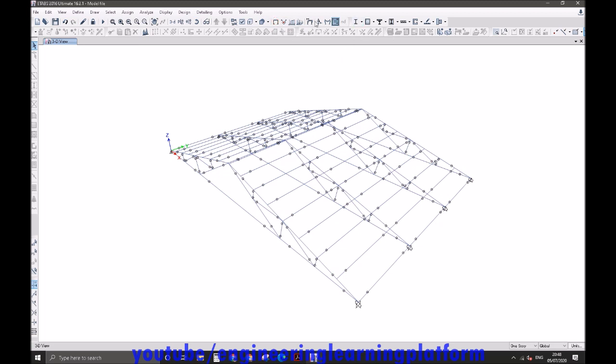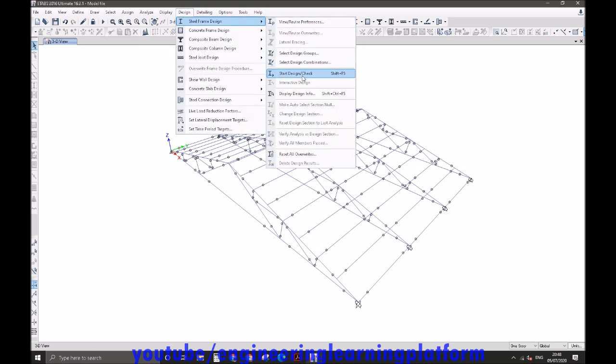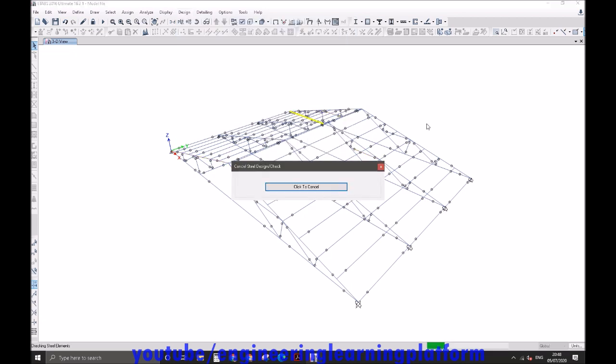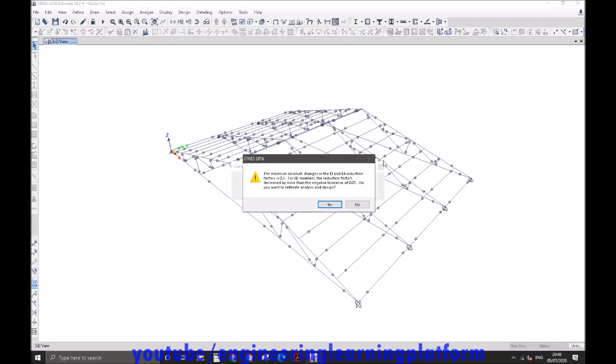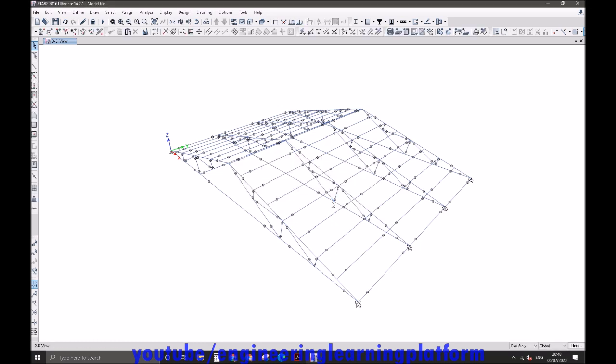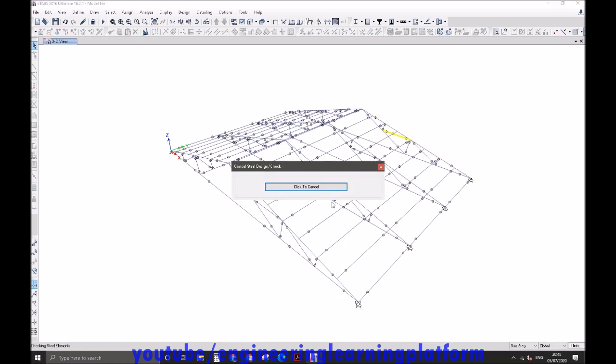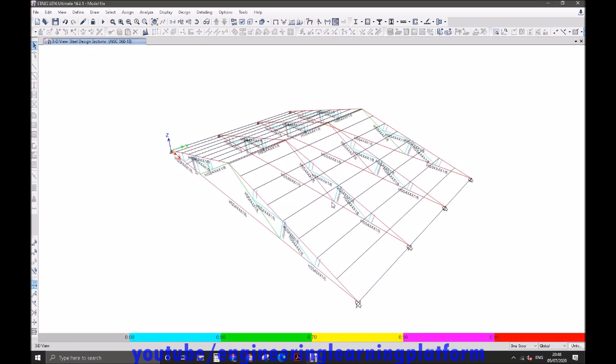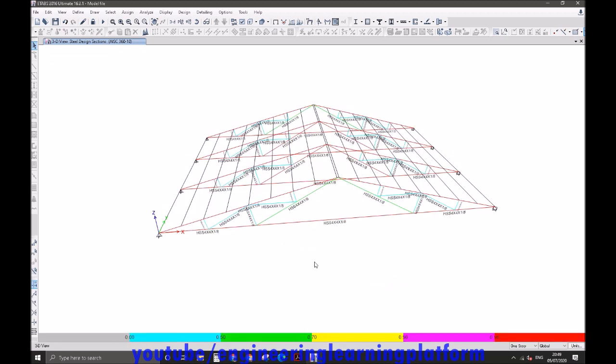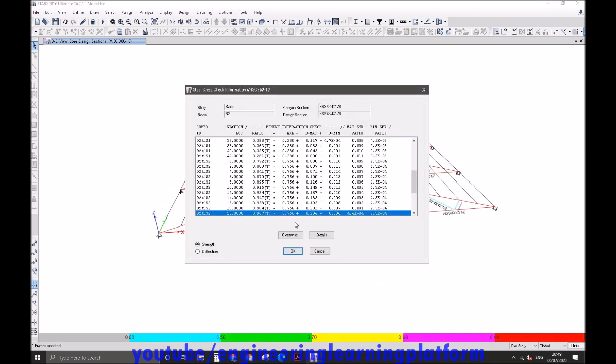Okay, so let's go to deformed shape and start with the design of steel structure. Of course, there are many iterations in the design, so this is our first run. We'll revise the failing members and change some overrides. So you see there are a lot of failing members that are in red, but not all red color shows failing members. The black colored members are not designed. I'll show you the reason in the later part why they are not designed.